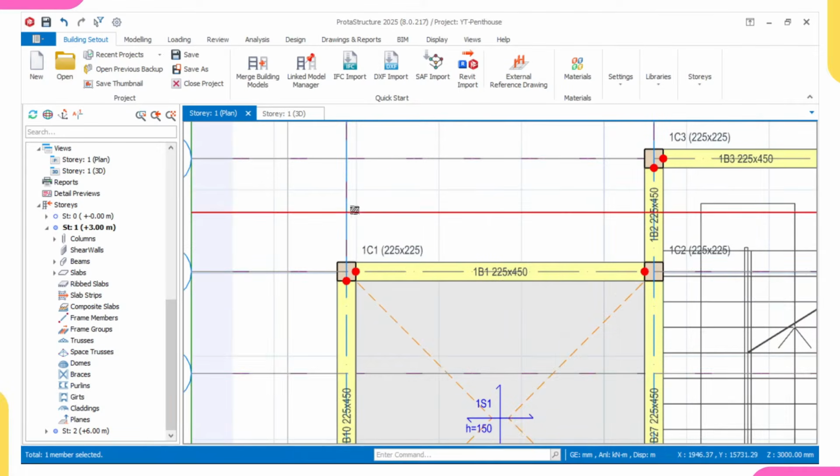But there's something I want you to understand. Naturally, this is a duplex, and we can rest a column on top of a slab, like a normal construction. If it's a duplex, a one story building, you can rest a column on top of a slab. But if it's a 2-story, 3-story or 4-story building, please don't rest a column on top of a slab. I'm begging, please don't do it. But for a duplex, the only thing coming to that column is the roof load, so you can rest a column on top of that slab.